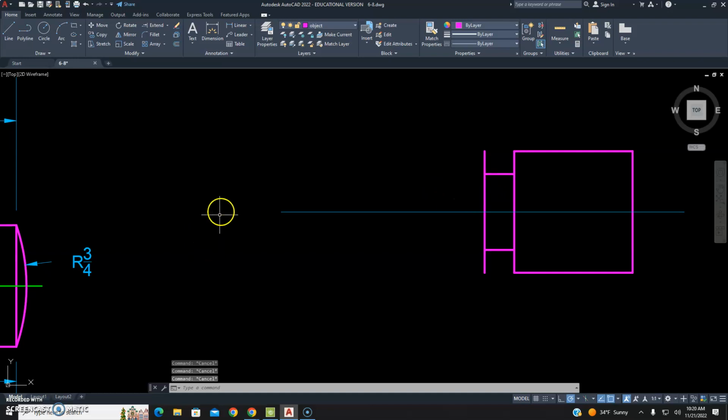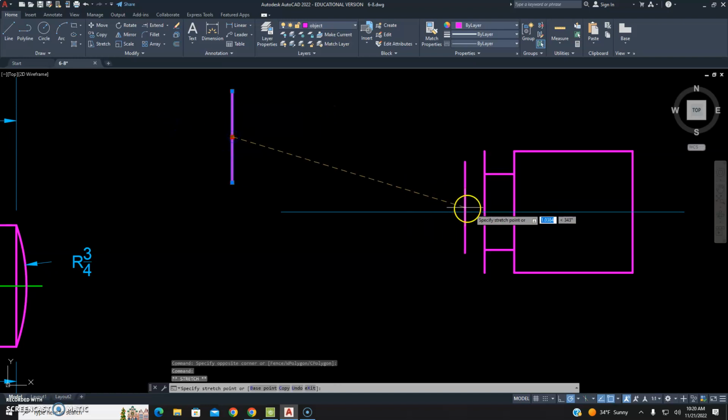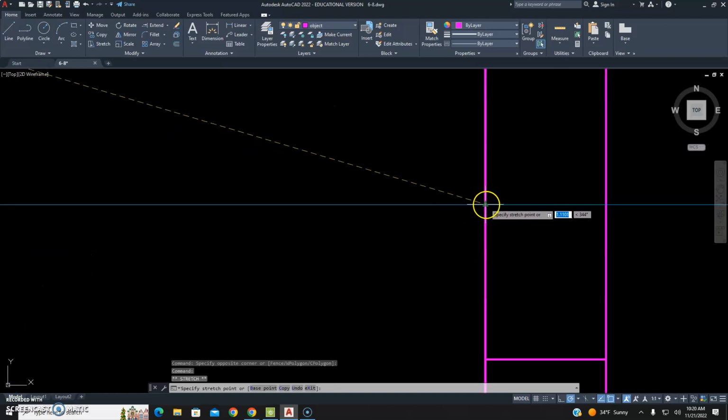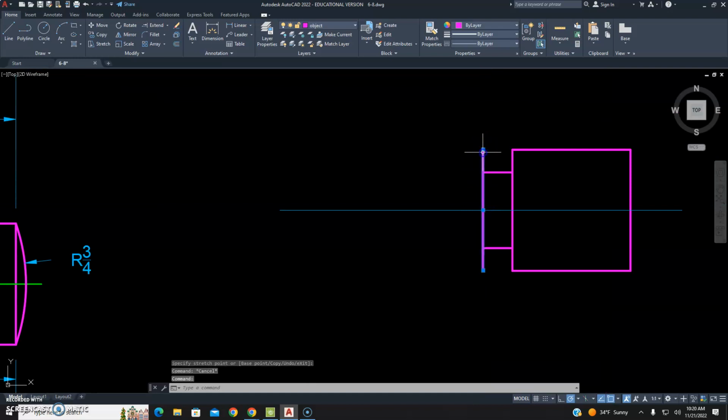Actually, better yet, let's do our 3/8 first. So we're making 3/8 in diameter, so we'll do a 3/8 inch line there. We'll pop that right in place there. We'll click here and delete our 1/2 inch line. And we've got our shoulder, and we said that that's 3/16 wide, so we'll offset 3/16 and bring that to our left, and just draw a line to connect it up.